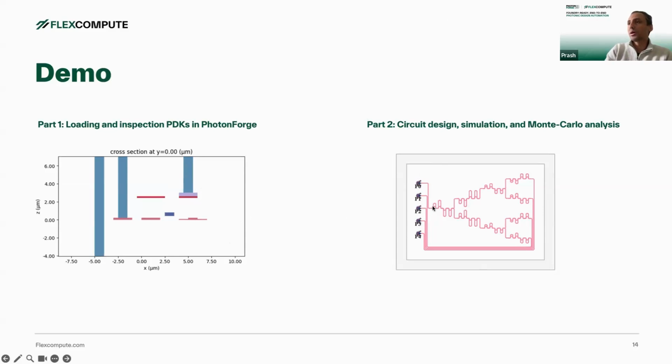And then the second part is we'll see how we can seamlessly go from simulating individual components directly from layout to actually doing the schematic driven layout for a relatively complex circuit, in this case this CWDM, and doing circuit simulation and also Monte Carlo analysis.